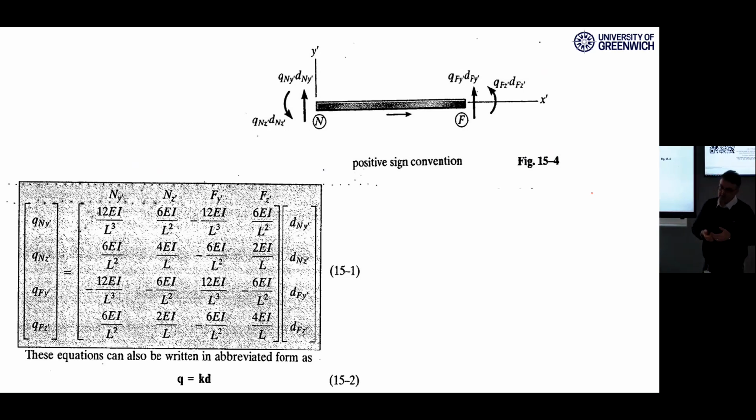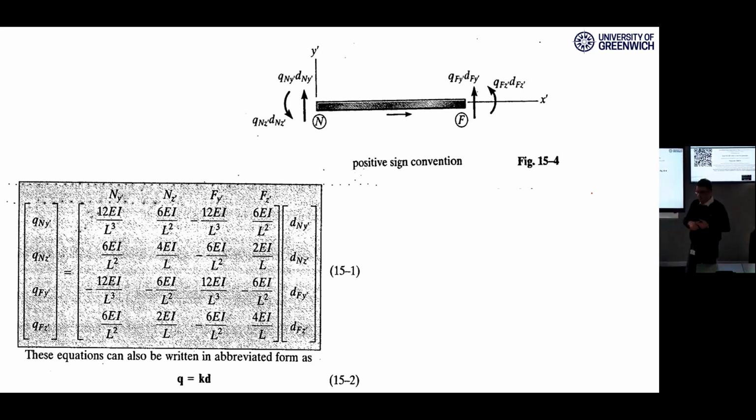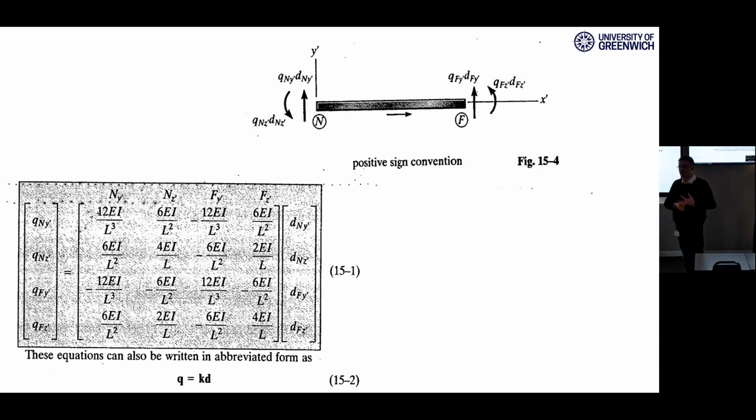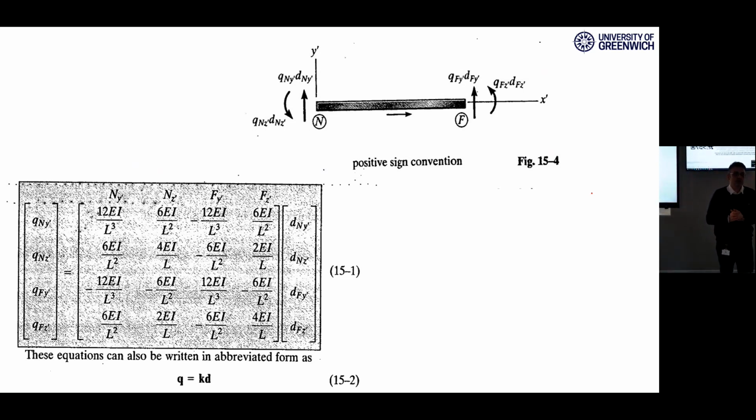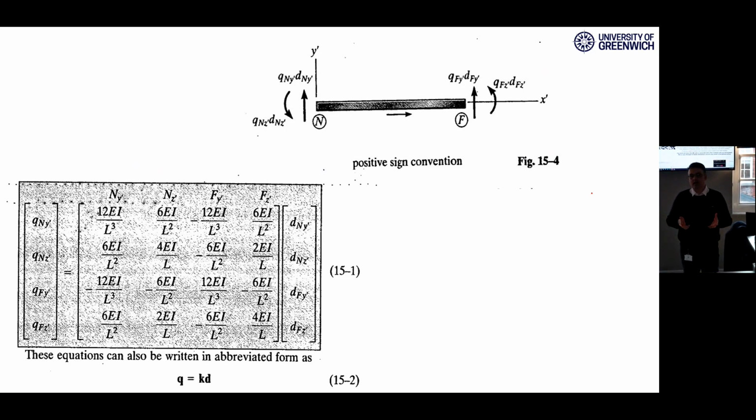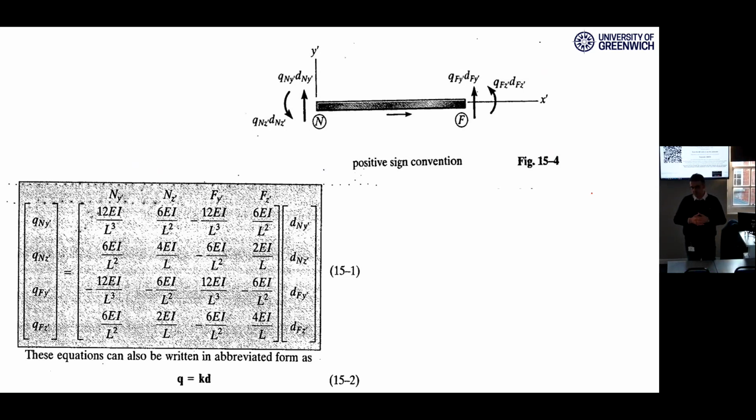Shear forces and bending moments are not present in truss structures, but they are in beam elements, right? But usually beam elements do not have axial forces. So that's the difference. If it has everything together, it would be a column, not a beam, right? So we anticipate a beam element has internal shear forces and bending moments, not too much axial force.